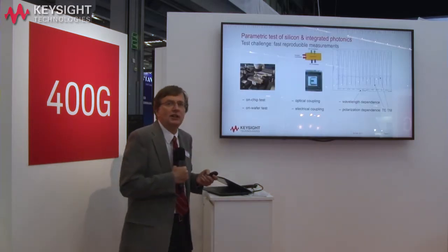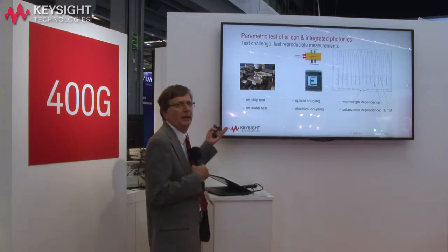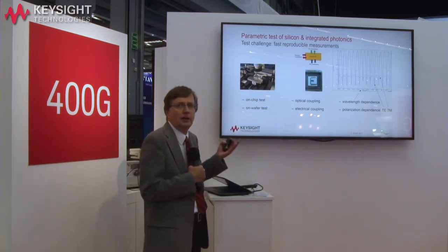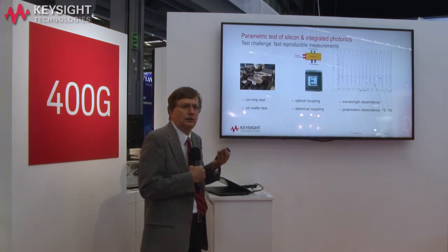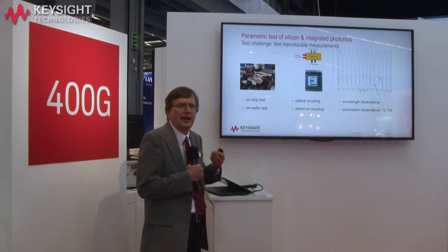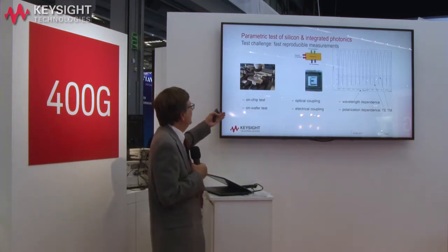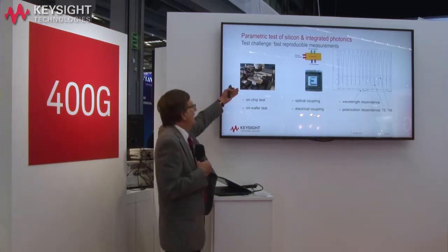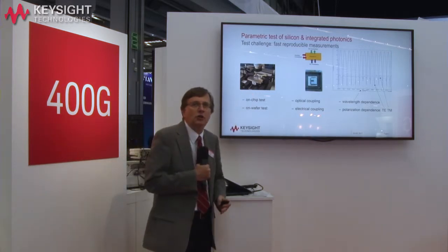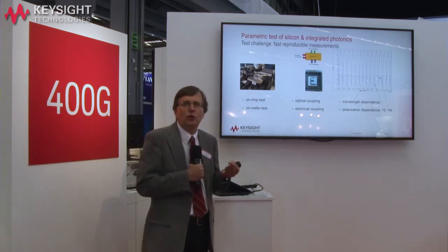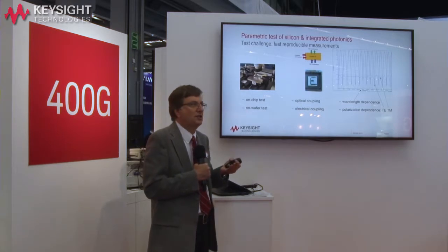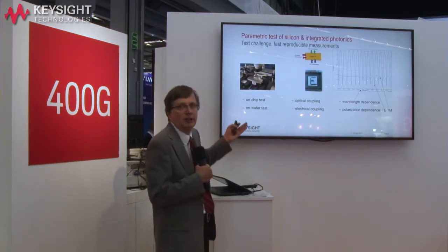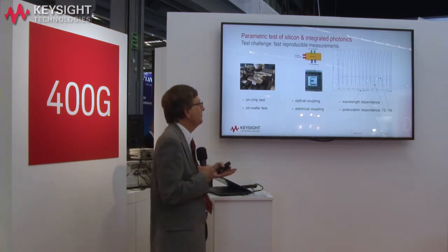So if we think about what we need to do when we're making measurements on devices that we're making, photonic integrated circuits, this is something that we want to increasingly do at production levels of scale, of speeding it up. And so some of the things that come up are, first of all, how do we couple signals in and out of the device before they've been packaged and we have permanent connections to them. So we have to do that with optical coupling, with electrical coupling.